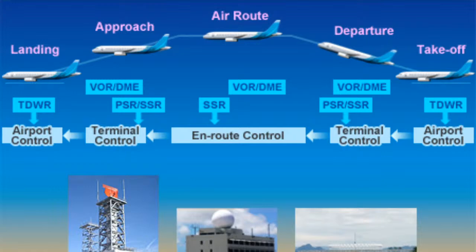It's an air traffic control technique by which we try and give a continuous descent from the cruising altitude all the way to the ground by relying on the pilot telling us when they are ready for descent, for continuous descent. And then we try, it's not always possible, of course, because sometimes there's traffic, but we try and rethink a little bit the way in which we work to allow for continuous descent.